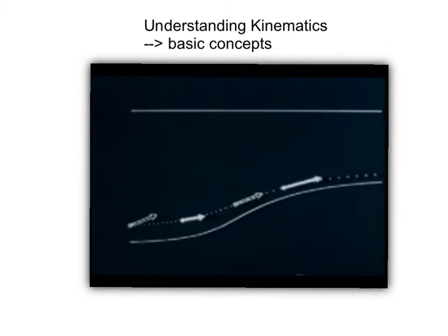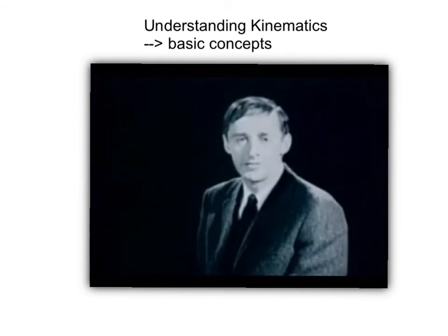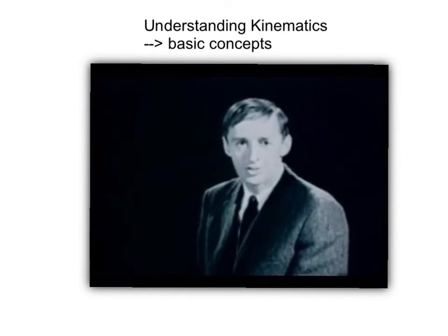The velocity that a fixed probe would see is the velocity of the material point that is passing through the laboratory point at that instant. It's an advantage of the laboratory coordinates that there's often a frame of reference in which the Eulerian field is steady.